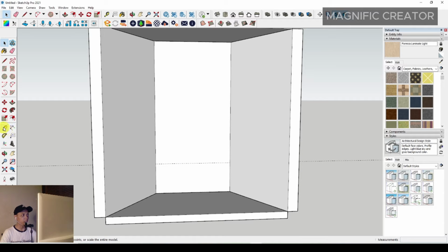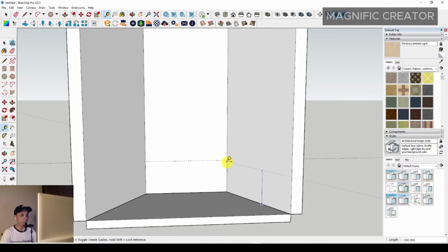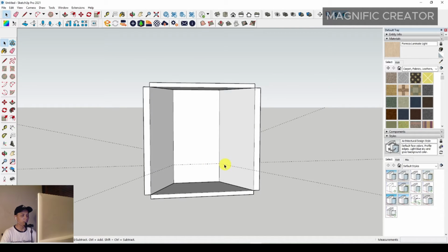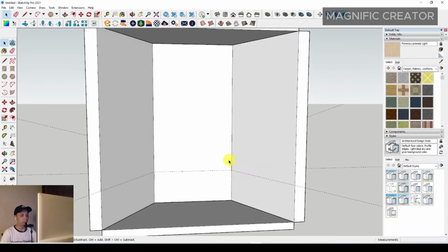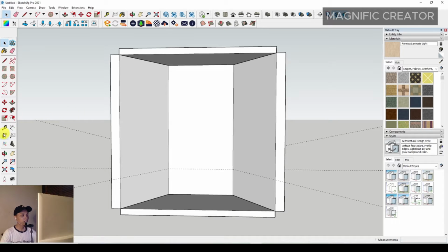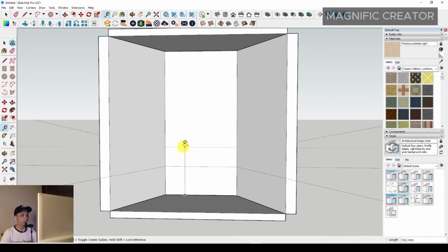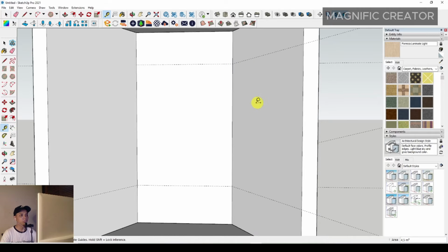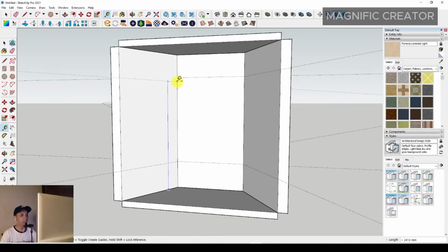And then you can also adjust it and set the same elevation between the floor and the guideline. And after that you can set the upper level of the window. You can set the upper level from the floor at around 2500 millimeter, and you can continue to the right or left side.